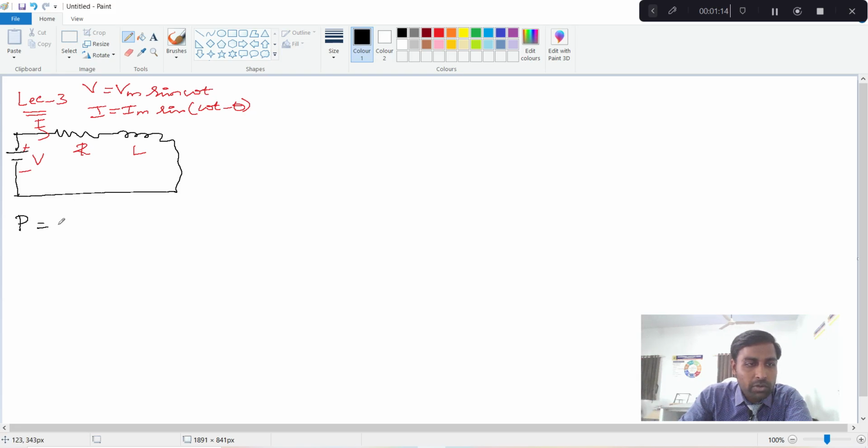Power, we know, is V into I, the instantaneous power. So I am just going to multiply these two expressions: Vm Im sine omega t times sine of omega t minus theta.